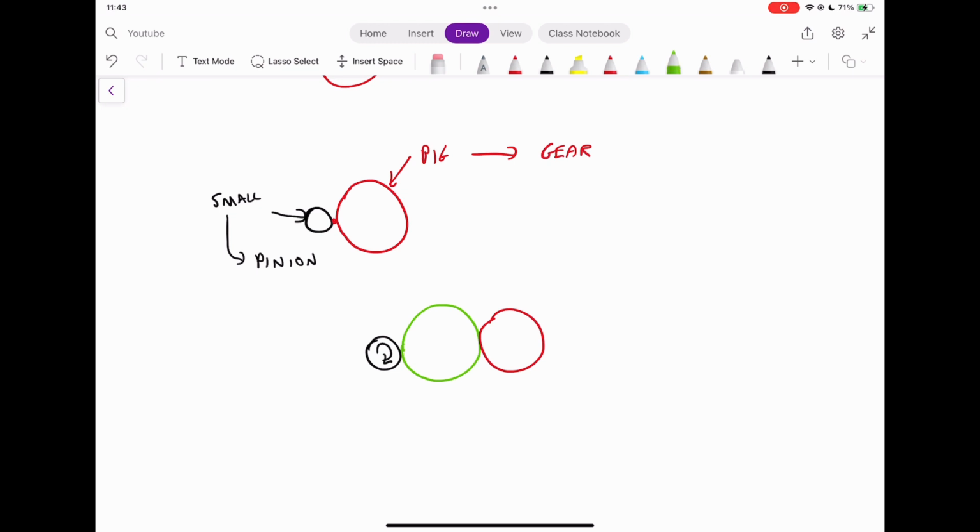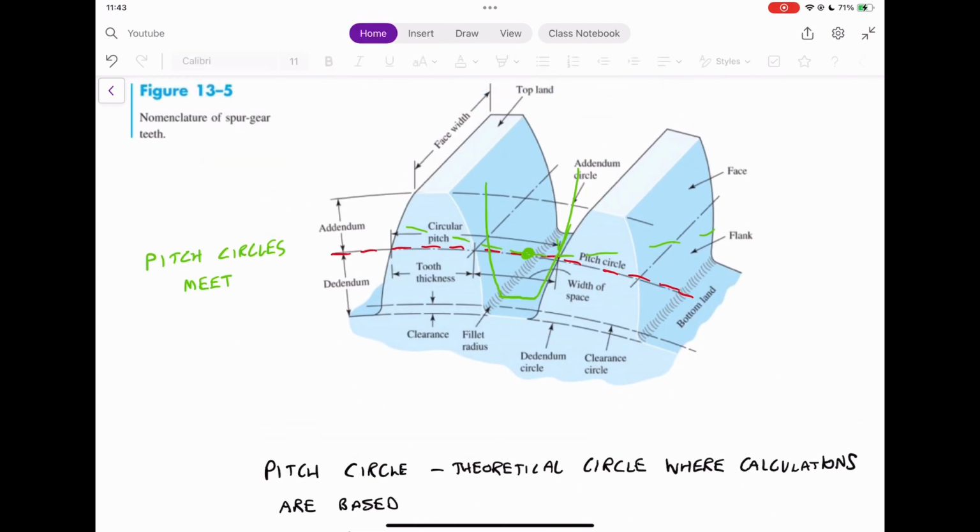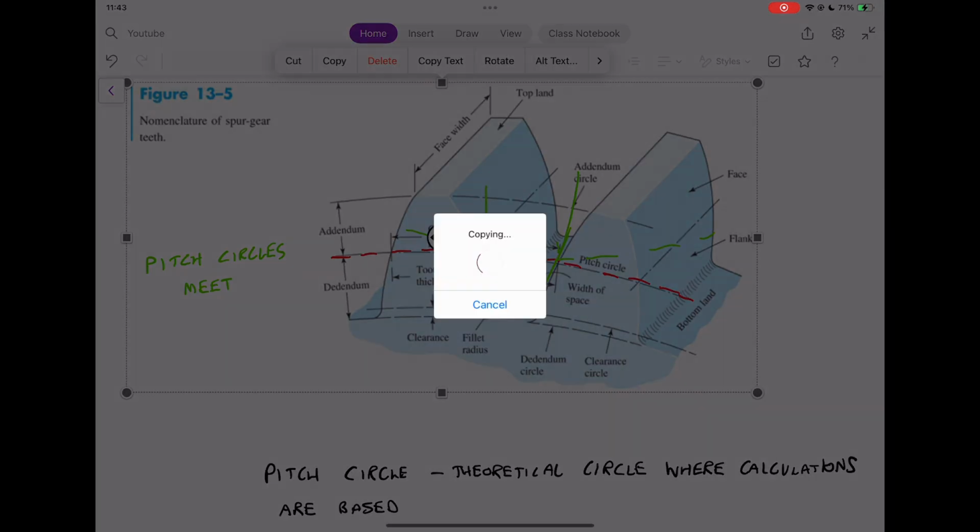The other thing we need to learn is that whenever there are three gears put together, the middle gear is there just to change the direction of the gears. That one is called an idler gear, and it essentially just transmits forces from the pinion to the gear. We use an idler gear if we want the pinion and gear to rotate in the same direction, or if we need more space between where we are transmitting the force from the pinion to the gear, or vice versa.